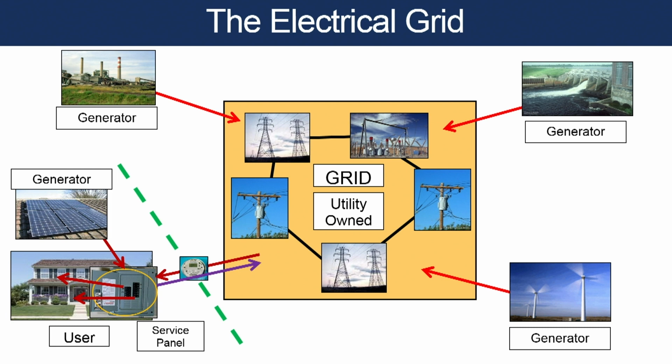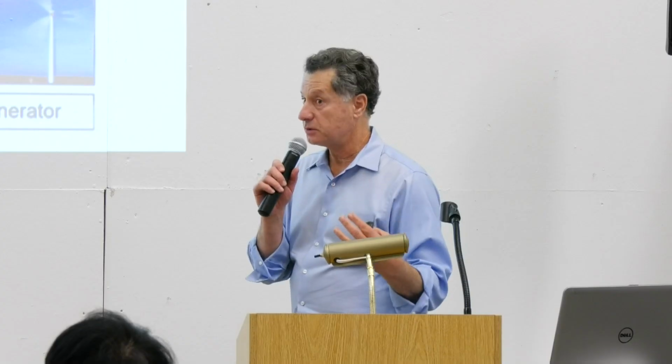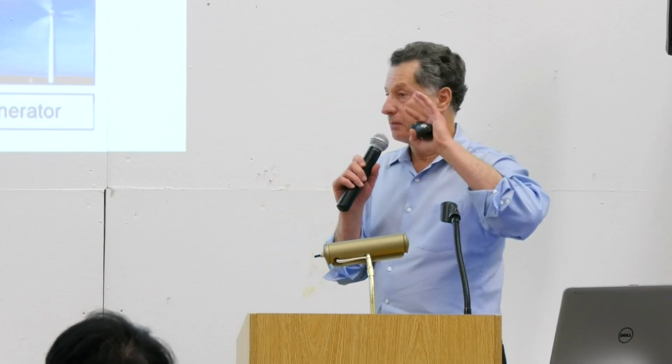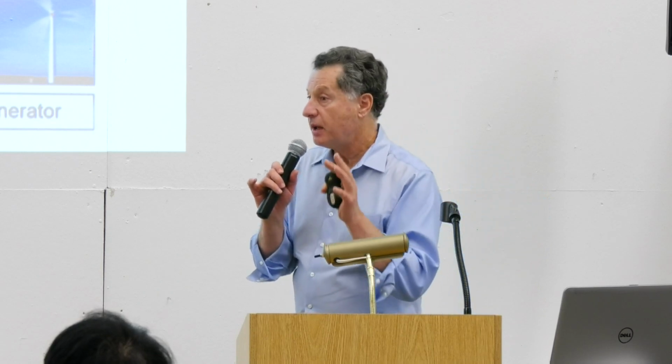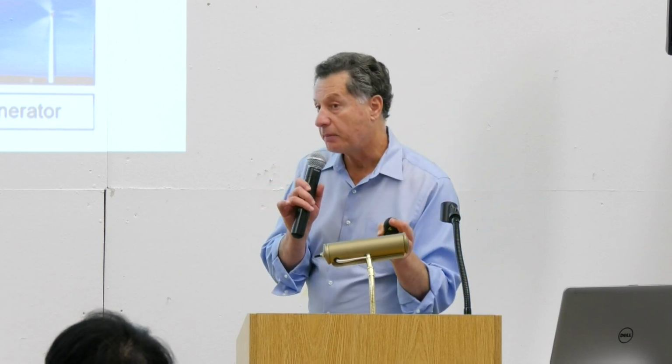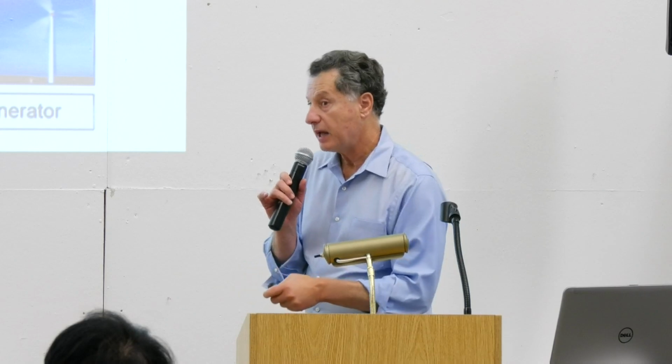So you've got this really elegant net metering solar thing where this does all it can, and the utility fills in seamlessly. It absorbs your excess, and it fills in your shortfall. So that's how it all works in commercial buildings, and that's why you don't need to have batteries on the site to do this accounting on a yearly basis. Now, batteries are big in the news, particularly with the power shutdowns. There's a booming market in trying to help batteries. Batteries can add value and help you back up, but the net metering systems don't need batteries.